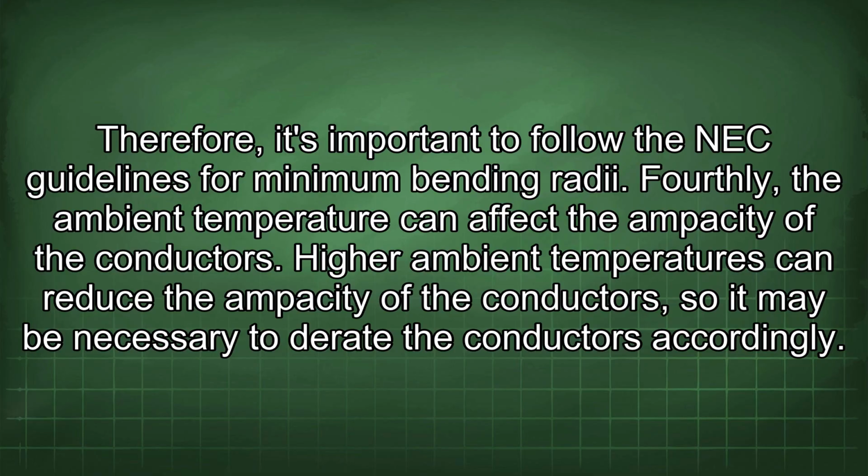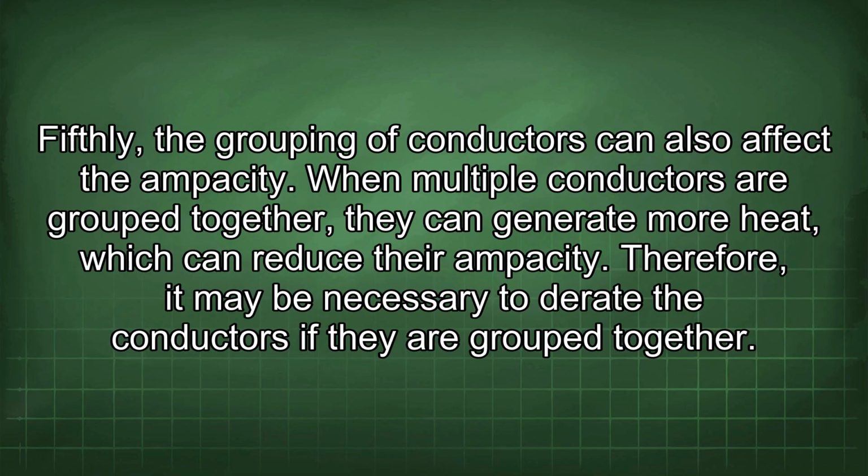Fourthly, the ambient temperature can affect the ampacity of the conductors. Higher ambient temperatures can reduce the ampacity of the conductors, so it may be necessary to derate the conductors accordingly. Fifthly, the grouping of conductors can also affect the ampacity. When multiple conductors are grouped together, they can generate more heat, which can reduce their ampacity. Therefore, it may be necessary to derate the conductors if they are grouped together.